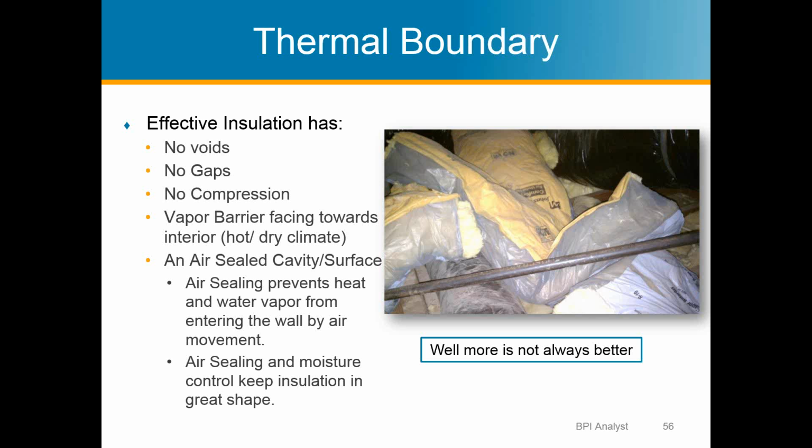So ideally, every time you put a piece of insulation in, whatever cavity it's going in is completely air-sealed. If you're doing a stud bay, you've got 5 sides of the stud bay there. Typically, when you put a piece of insulation in, you could caulk the seam of all 5 of those sides, and then when you put the drywall up, you could caulk the face before you put the drywall up, and then you would have a completely sealed cavity.